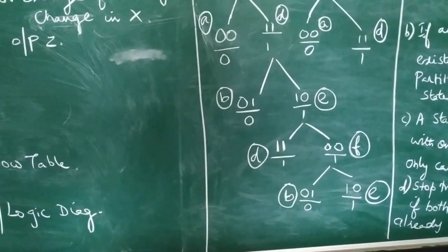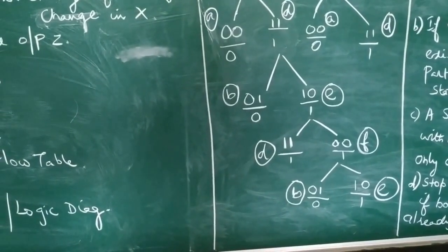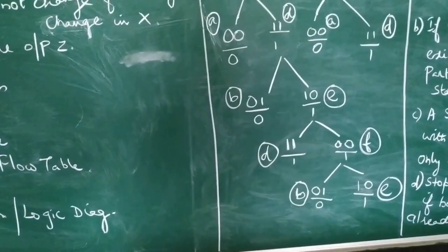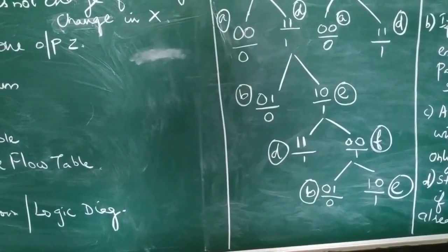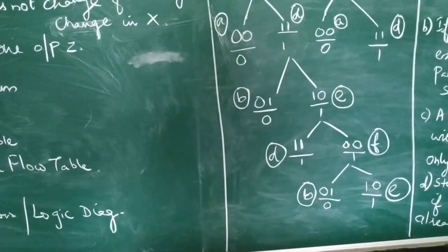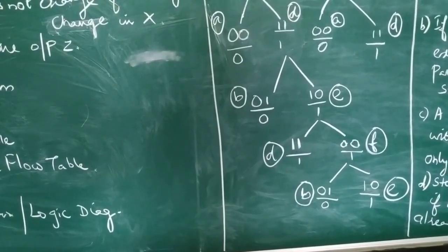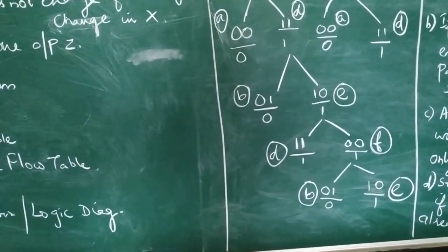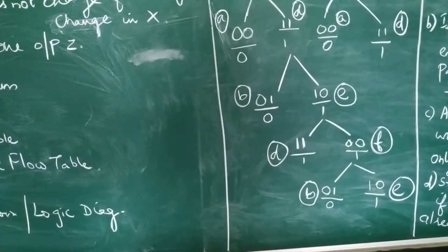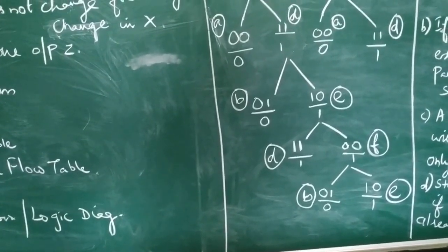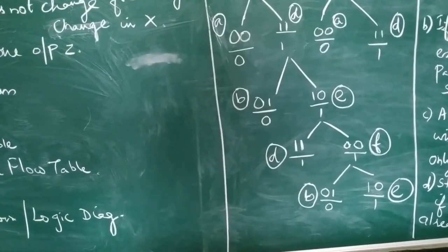So here y is equal to 1, x equal to 0. When y is equal to 1, z, the output in the denominator, is equal to x value. The x is 0, so it is a 0. And for the next one, x equal to 1, E state, x equal to 1 and y is equal to 0. When y is equal to 0, the previous output is our z. So the previous output is from the F state, that is 1, that we have written here.